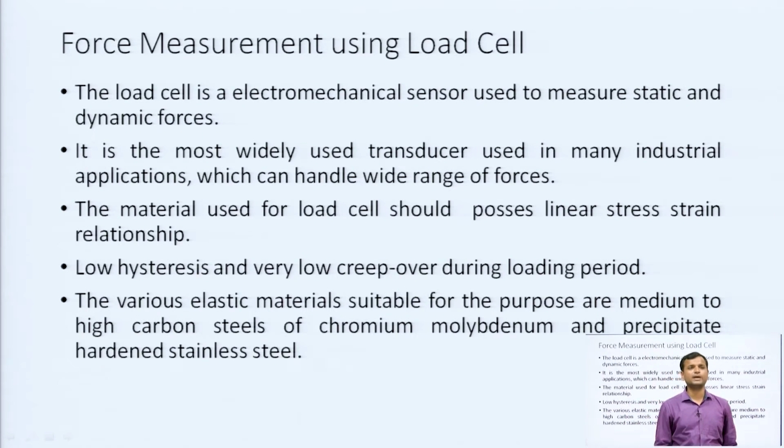The next arrangement is force measurement using the load cell. So, the load cell is an electromechanical sensor that is used to measure the static force as well as the dynamic force. It is the most widely used transducer in many industrial applications, which can handle a wide range of forces. The material used for load cell should possess a linear stress strain relationship.